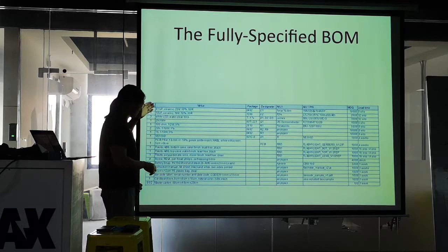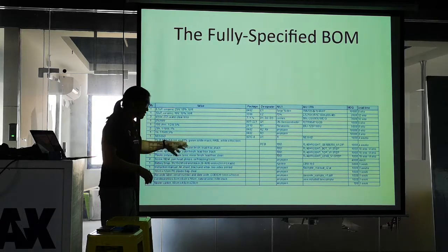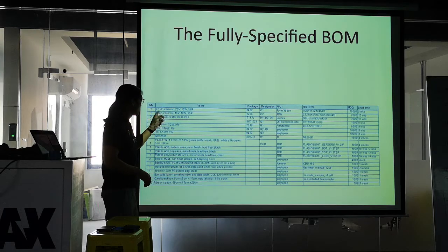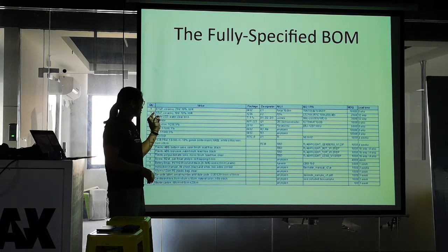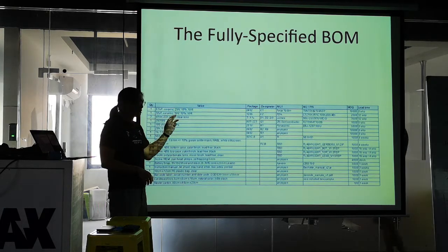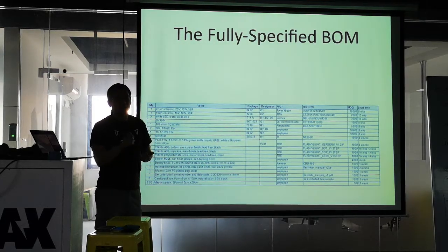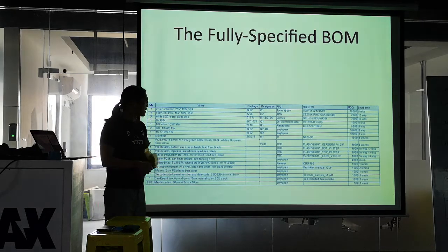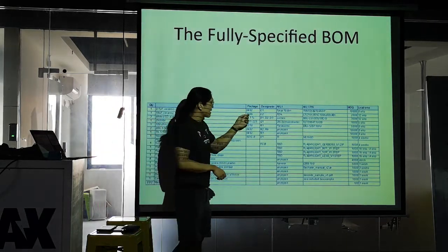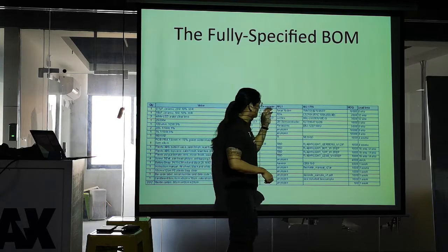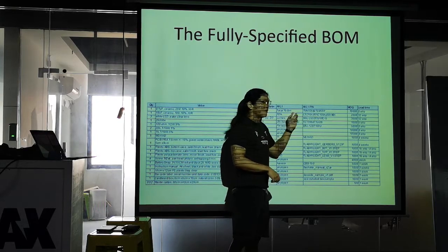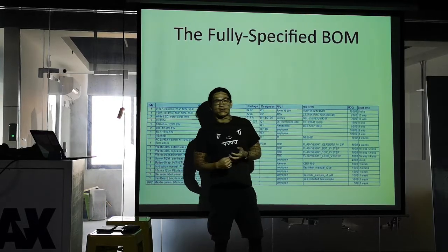So the quantity is here, the description is here, right? But now that 10 microfarad capacitor is described as 10 microfarad ceramic, 16 volt, 10% X5R, right? So you've now covered all the bases. What's the voltage? What's the dielectric? What's the composition, right? You have the package, you have the designator, and then you have these things called AVLs, authorized vendor lists.